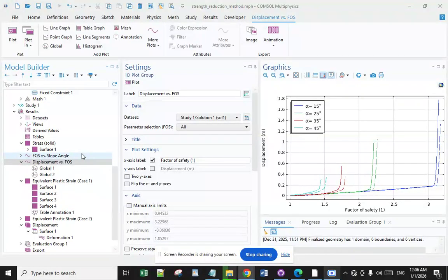By this definition, a structure with an FOS of exactly 1 will support only the design load and no more. Any additional load will cause the structure to fail. A structure with an FOS of 2 will fail at twice the design load. The chapter of margin of safety.